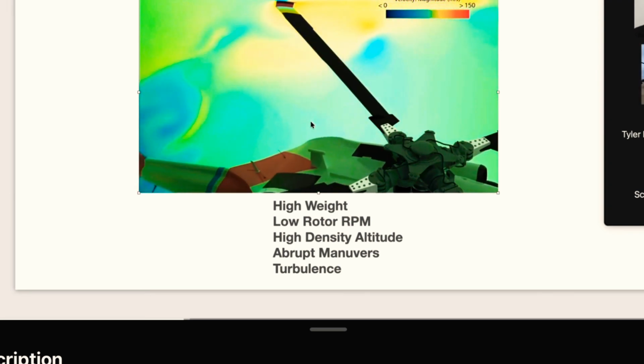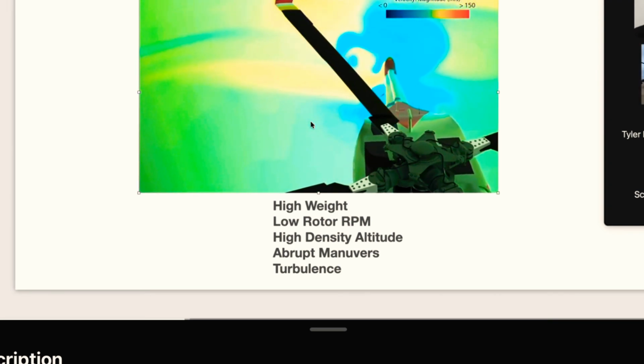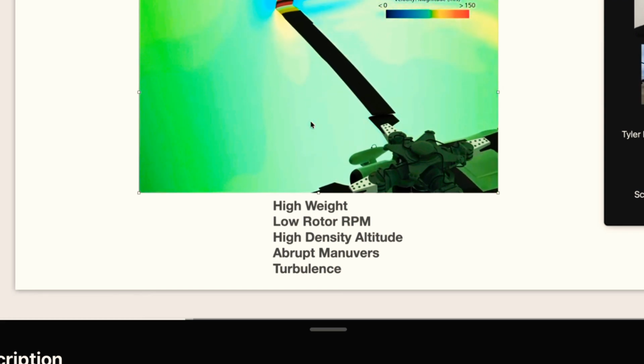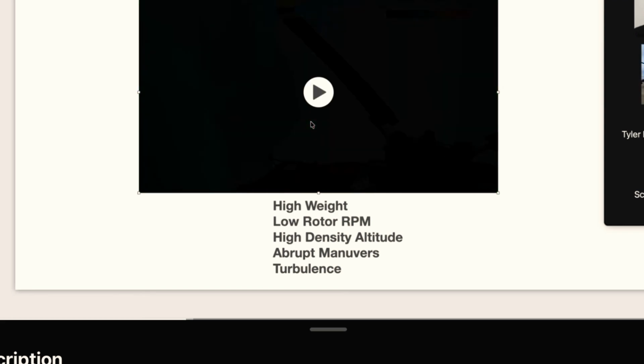This is generally considered a self-correcting maneuver because as we pitch up, the helicopter is slowing down, and as we slow down, we're reducing the angle of attack on the retreating blade, and that's ultimately the goal. But the most effective immediate action is to lower the collective, and that will reduce the pitch and the AOA of all the blades, breaking the stall. Only after we've reduced the collective can the pilot add aft cyclic to slow the aircraft.